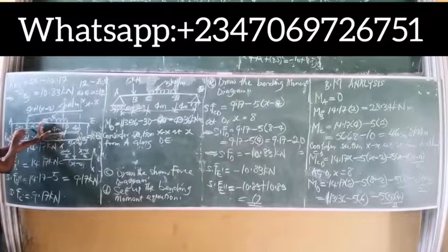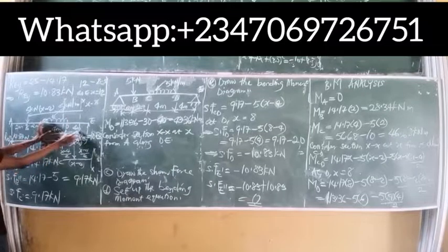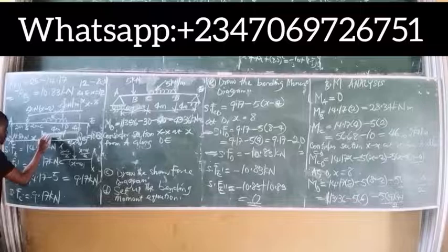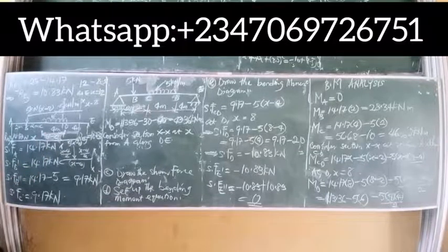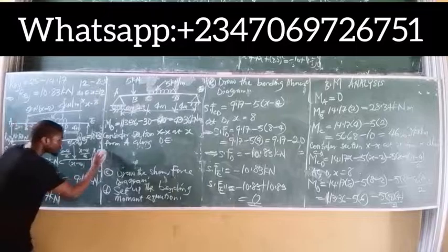2 plus 2 is 4, plus this 4 is 8. Simply remove that 8 from x. It gives you x minus 8. That's the length of the UDL. Is it clear? Okay, so that gives you the length of the UDL. But it doesn't end here. Now let's take moment about DE. This one becomes moment along DE.